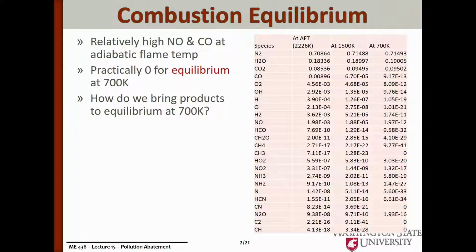is occurring, there's a significant amount of dissociation of carbon dioxide into carbon monoxide. And at that temperature, when there is a number of free radicals of oxygen, you're actually also going to get some nitric oxide formation within the engine compartment. Now, at the temperature that we typically exhaust the gases out of the tailpipe, there's practically zero nitric oxide and carbon monoxide at equilibrium. But at the flame temperature, there's a significant amount.